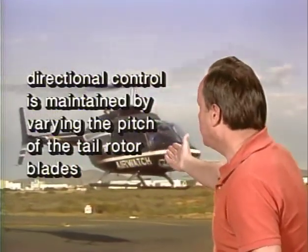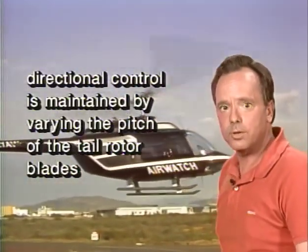Now, let's assume you're in a hovering helicopter and it's equipped with a tail rotor, as this one is. How do you maintain directional control? And the answer is by varying the pitch of the tail rotor blades. You, of course, do that with pedals.